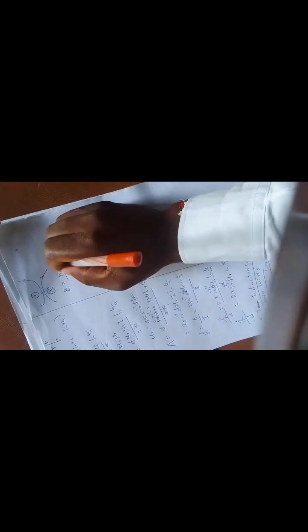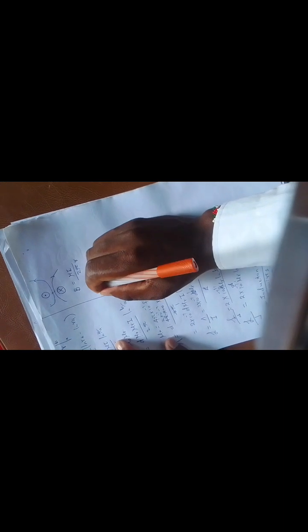Now remember we defined that at any distance r we're considering, the inductance will be from a particular distance r. At any distance r, we'll have magnetic field lines, as we stated the formula earlier, to be mu times current over 2 pi times r. That is, we're considering these two wires from a particular distance, let's say it is r. Now, we'll say the total flux linkage due to the two wires for a length, and we take the length of such two wires to be d.